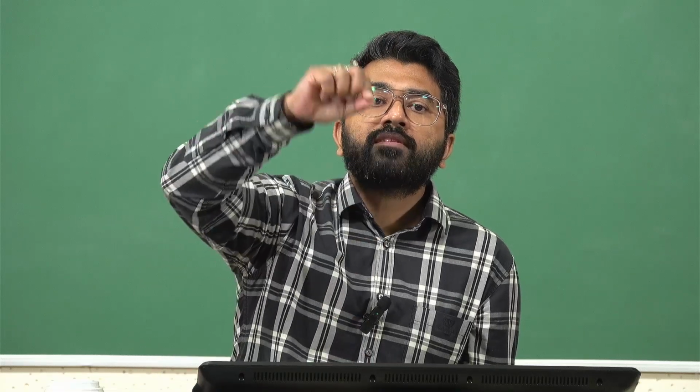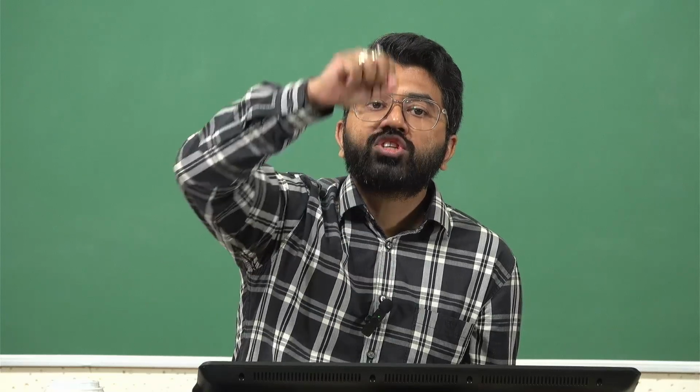So let's say I have a rectangular specimen of length 5 centimeters, a width of 1 centimeter and a thickness of 3 millimeters, right? So what is the area of cross section? It is 1 centimeter times 3 millimeters. That's the area of cross section, that's my initial area. If I divide the force at any point by this initial area, I'm just normalizing all the force points by the area, and I'll get the stress value. So stress keeps on changing as we keep on pulling the specimen, right?